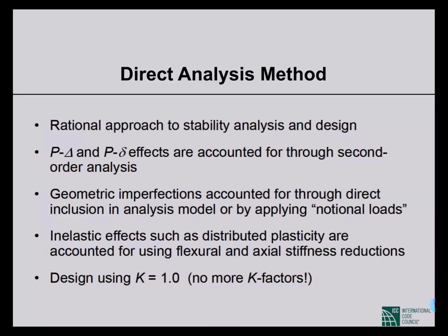Geometric imperfections are accounted for through direct inclusion in the analysis model or by applying notional loads. Now we'll talk about notional loads. Yesterday we didn't talk about notional loads. What is notional load? Now you can understand this is something related to geometric imperfections. So we consider geometric imperfection in direct analysis method by notional loads.